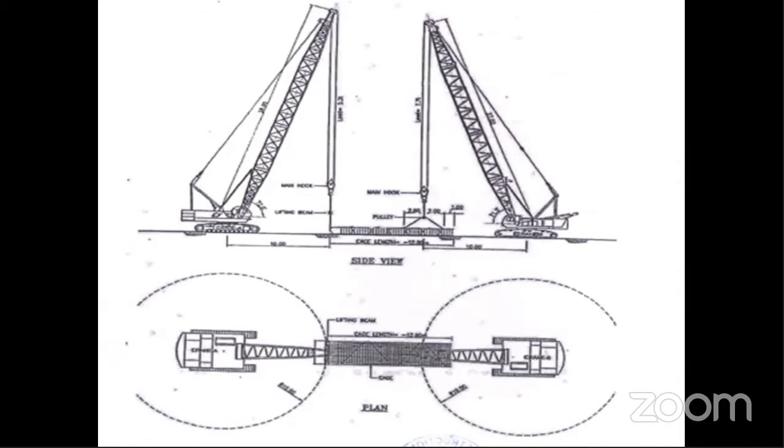This becomes a difficult one to do. See, in the drawing, two cranes have been shown. One will be a 50 to 75 metric ton crane, and the second one should be around 18 to 25, which is based on the site conditions and the weight of the cage.